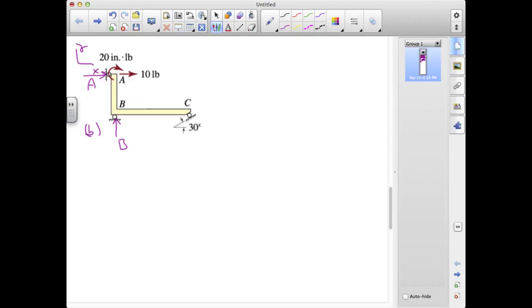We're able to move laterally parallel to that surface. So now our line of action for C does something like this. We have a 90-degree angle here. That makes this angle 30 degrees, and our C is inclined at that angle.